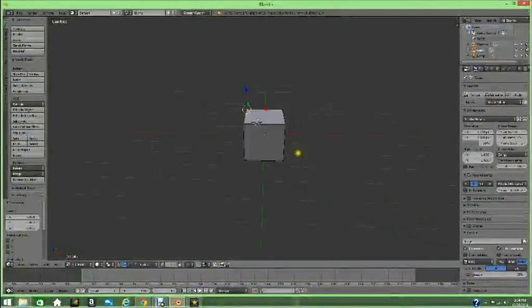Blender is not like most programs. You can't just left click everything to select. Left click just moves your 3D cursor around. In order to select, you must right click. Right clicking a vertex, face, or edge will select that vertex and unselect everything previously selected.